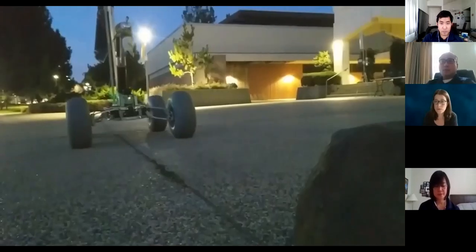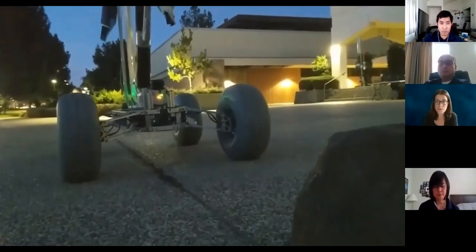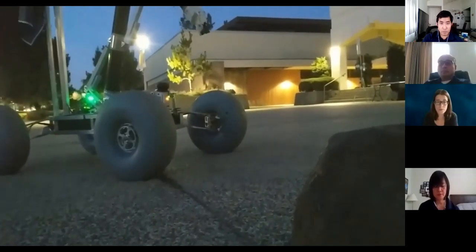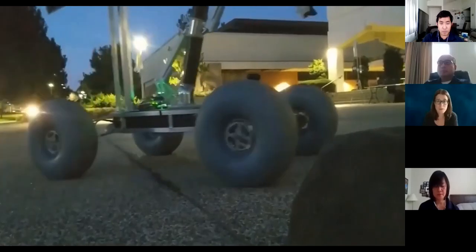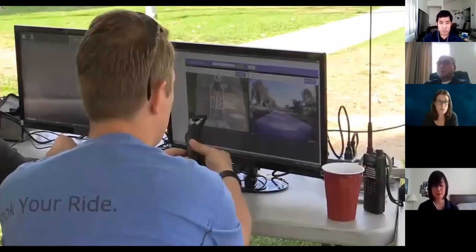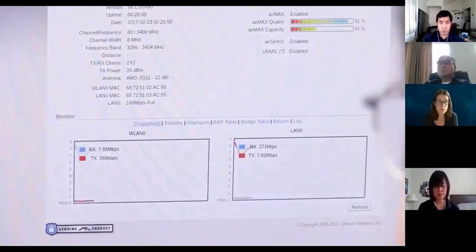Our sensor package uses a 2-dimensional LiDAR unit, a centimeter-accurate GNSS, and an IMU. These components allow us to continuously update our position within our SLAM model. The LiDAR is mapping the terrain, while the GNSS is localizing the position. By choosing Python in a module design pattern, we're able to seamlessly integrate these sensors to conduct unit testing and authenticate software verification and validation.